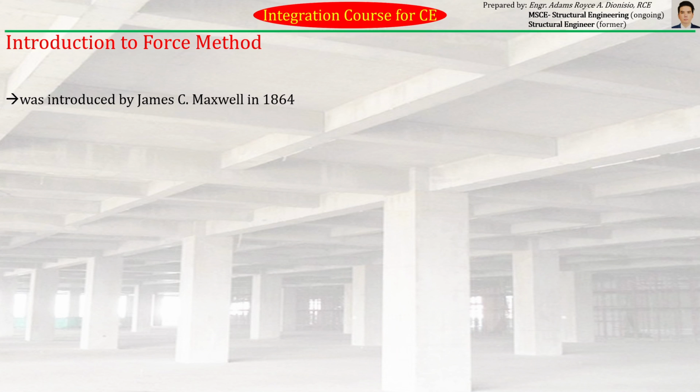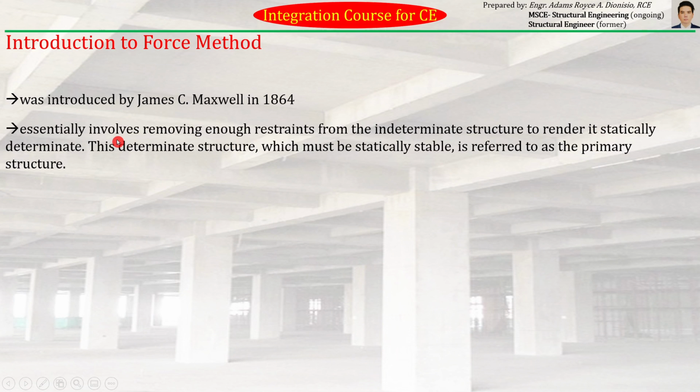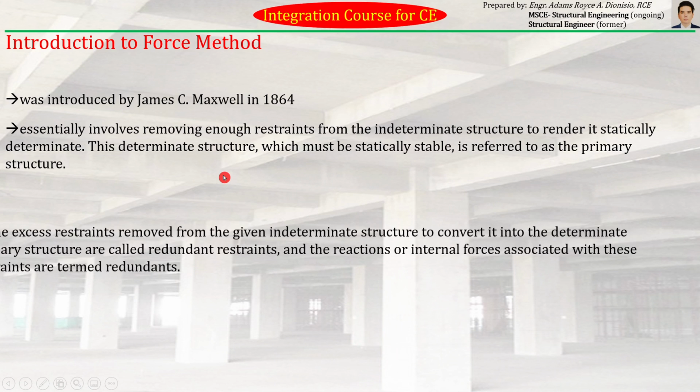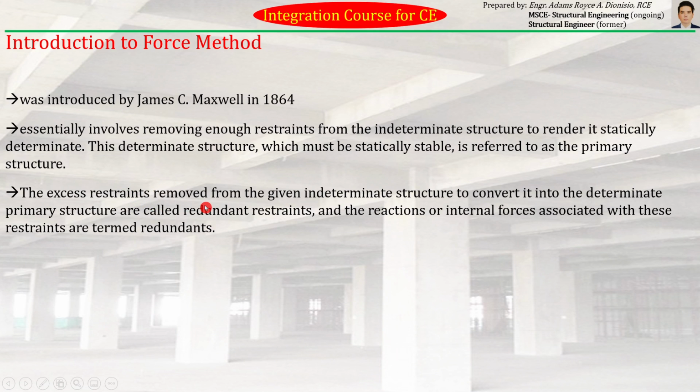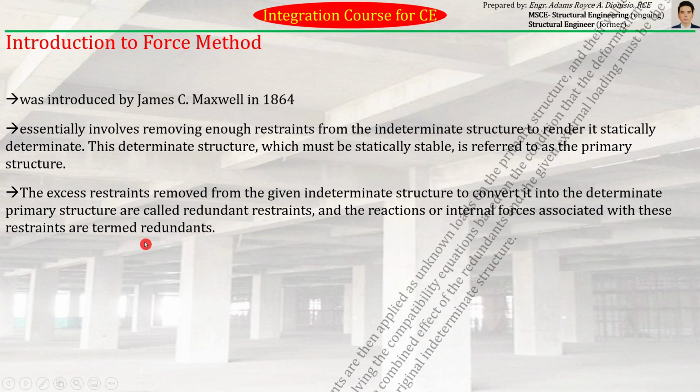Okay, so yung force method na to, or yung method of consistent deformation, this was introduced by James C. Maxwell in 1864. Essentially involves removing enough restraints from the indeterminate structure to render it statically determinate. This determinate structure, which must be statically stable, is referred to as the primary structure. The excess restraints removed from the given indeterminate structure to convert it into the determinate primary structure are called redundant restraints. And the reactions or internal forces associated with these restraints are termed redundants.